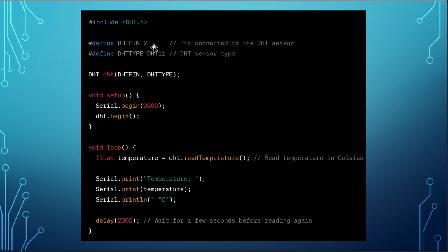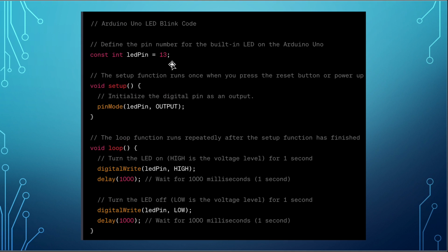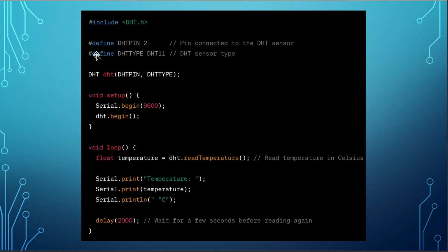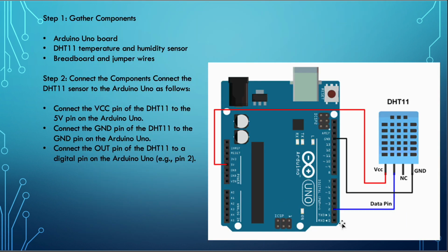So we are defining that pin, or here you can use the integer type. I think this is more valid, to name the pin we want: constant int name equals the pin, right? We know that we have made the connection on pin number 2.